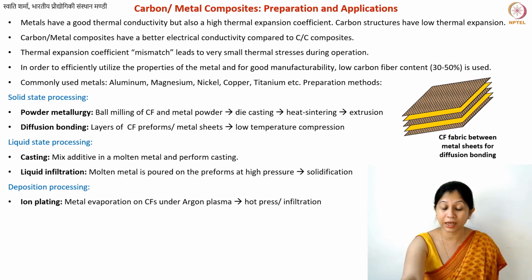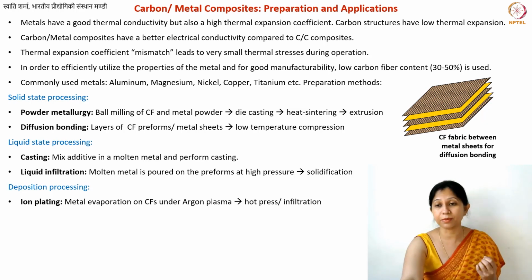What are we depositing? If you remember from the carbon composite class, we talked about pyrolytic carbon deposition on top of the carbon fibers, pyrolytic carbon from gaseous hydrocarbons. In this particular case, something very similar, but here you don't have the carbon being deposited, but the metal being deposited on top of your carbon fibers. This can be done using evaporation techniques.